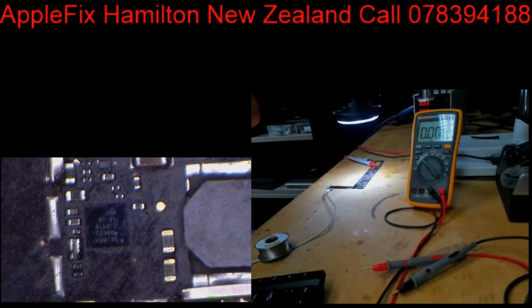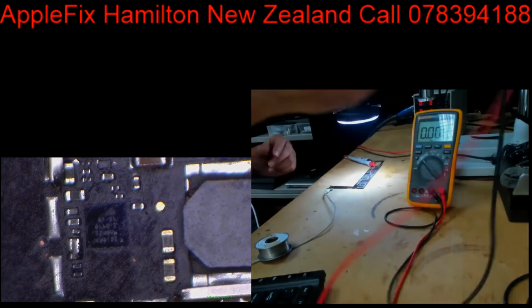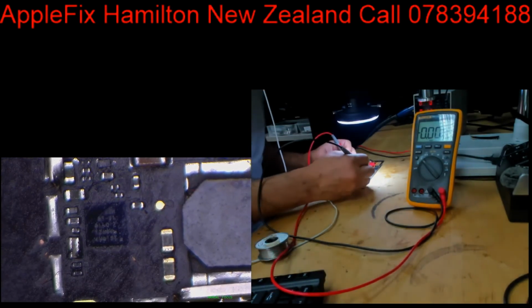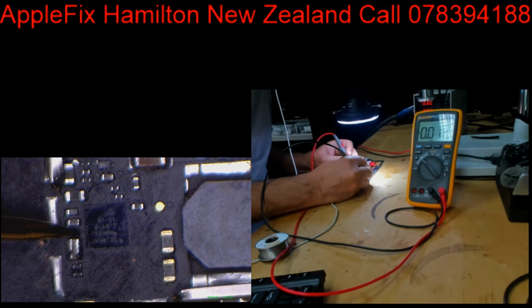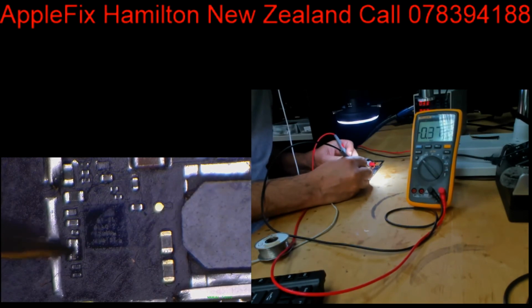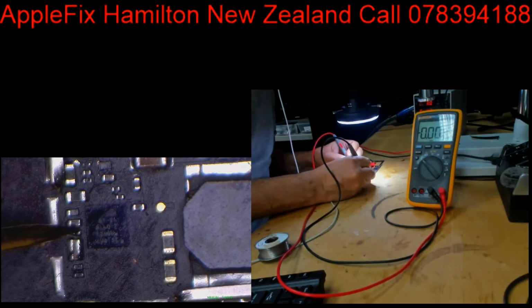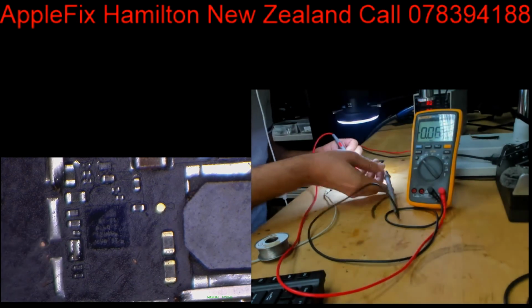So guys, now we will check if we got it right, and if we have got 3.3 volts. Okay, so yeah, that's 3.2, so we have restored the line, so it looks all good to me. So we should not have any problem charging and turning on this iPad. So we'll check one more time. Yeah, can you see? We have restored the line, so it's all good now.